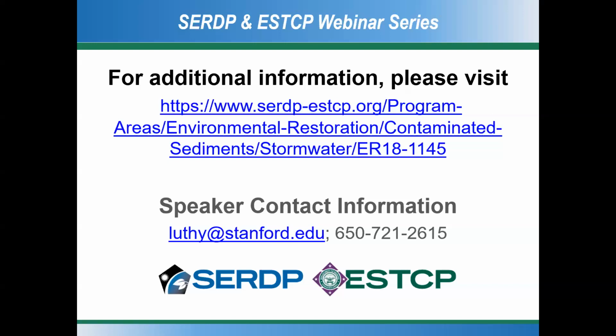Well, the answer to the second question is exactly right, that leaf litter will provide dissolved organic carbon. When we got the catch basin material from Naval Weapons Seal Beach, both what we saw at the site and what was shipped to us, there's a lot of straw there, from the fields around the weapons station. And so in this stormwater runoff, you have some dissolved organic carbon. It's not toxic, but it will sorb onto biochar and onto regenerated activated carbon.